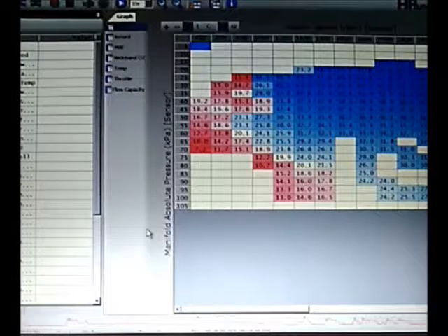The two wires that come out of the wideband should be a signal wire and a ground wire. All of the channels on the HPTuners module all share a common ground. So all your grounds, if you have more than one device hooked into it, are going to be tied to the same pin on the terminal block, but the signal wires are going to go to different channels.